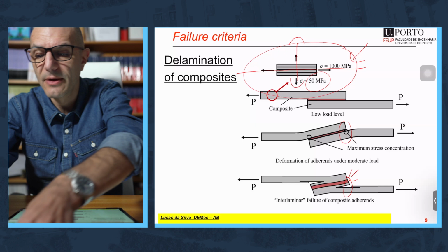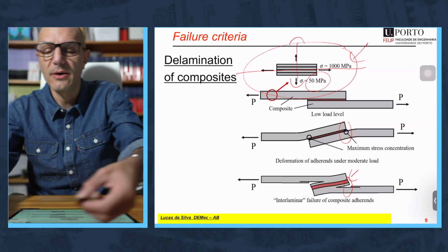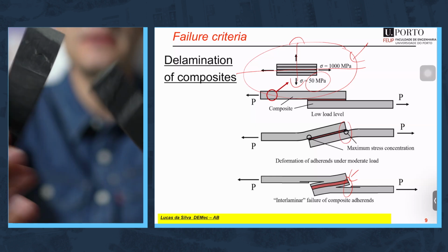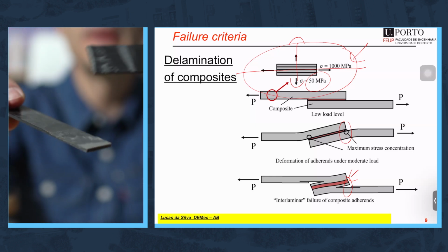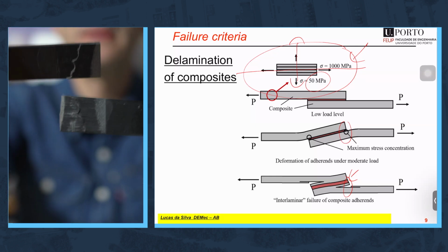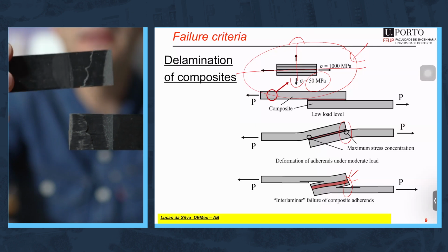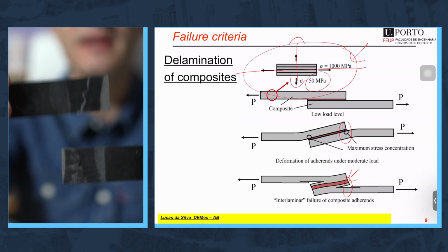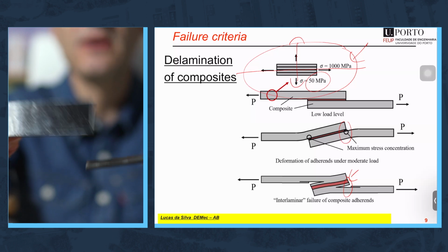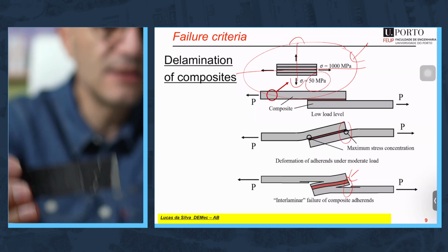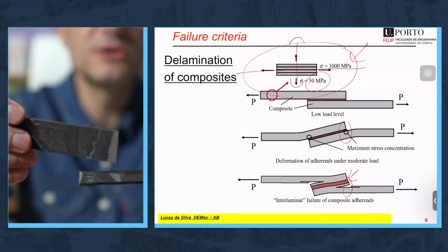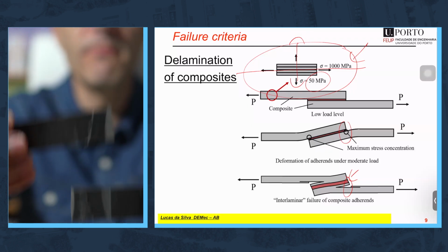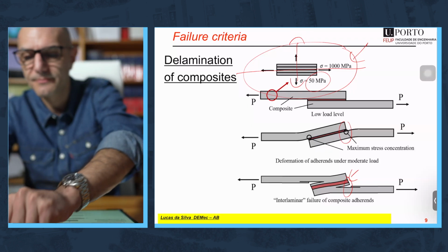Again, I have an example here where you have delamination of the composite, you see? Everything happened here and here at the ends of the overlap by delamination of the composite. This typically happens when you use a stiff adhesive, like an epoxy. That's why when you use composite, it's better to use a less stiff adhesive to avoid too much stress at the ends of the overlap so that the adhesive can work and can give its full potential. All right?